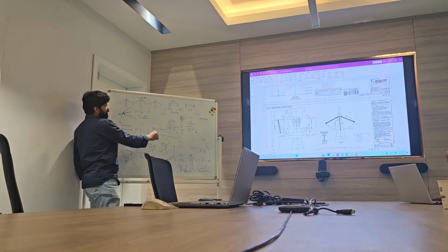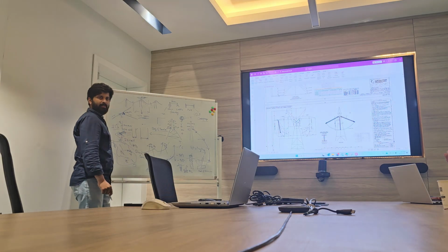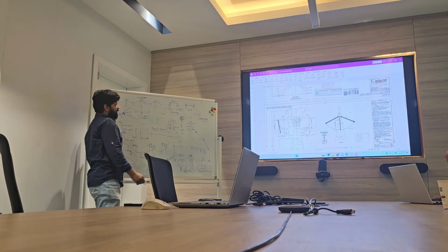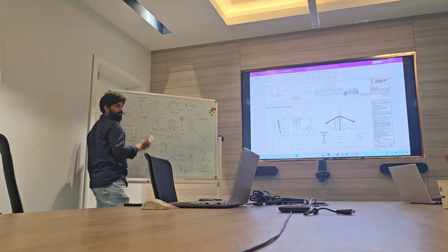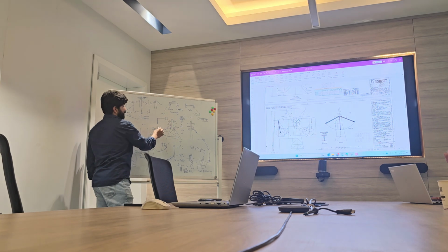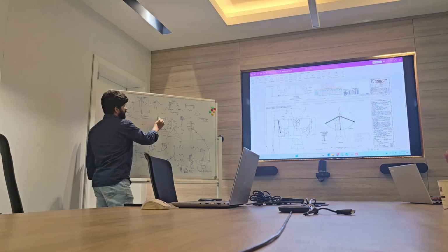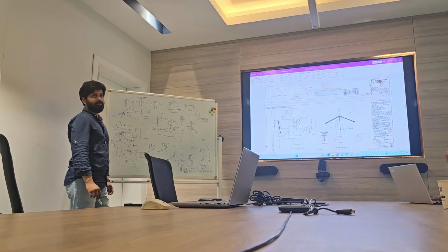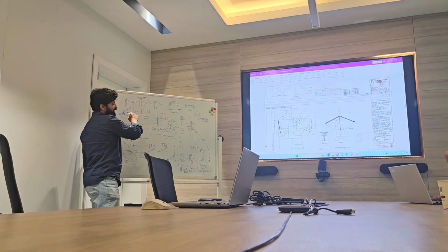Suppose you say a line has 90 degrees. So we have to construct a better line. When you have a 90 degree line deviation angle, suppose please look here. You have a substation here. My line is coming like this. My original line was supposed to go like this, but my final line is going like this. What is the angle here? 90 degrees. Always the line deviation is measured by extending the original line and measuring the angle.